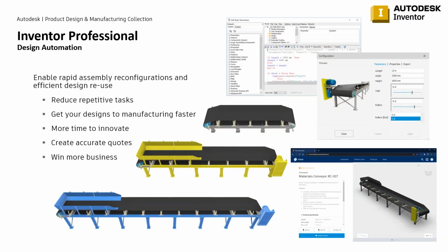There's also a fair amount of design automation built in. Probably about 13 or 14 years ago, iLogic was added to the Inventor product. And it really enables innovation and configuration inside of your product rather effectively. So you can have a rules-based design that says, for instance, I have this conveyor. It has these rules to it. It can be certain lengths, it can be certain widths, it can be certain heights. If this changes, then this also has to change. Things that you would go through in the minutia of doing on a daily basis, but can be more automated.